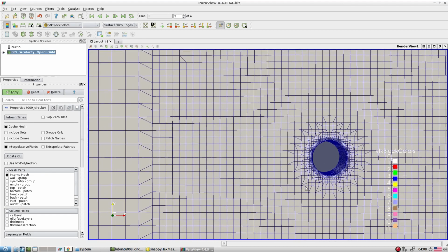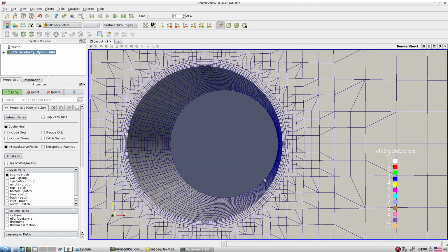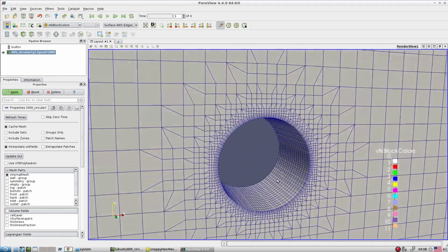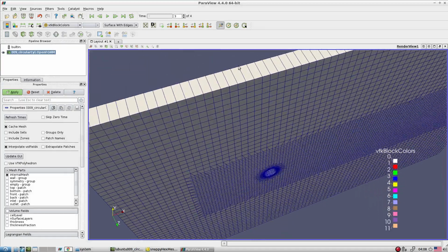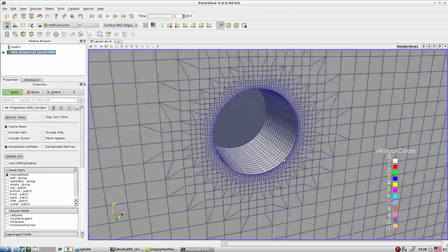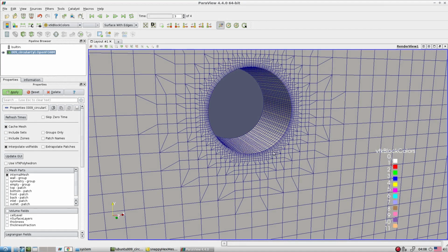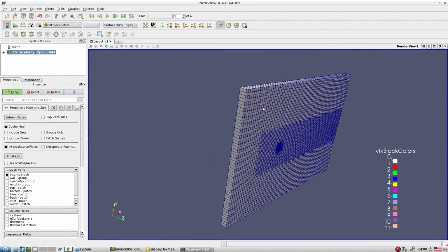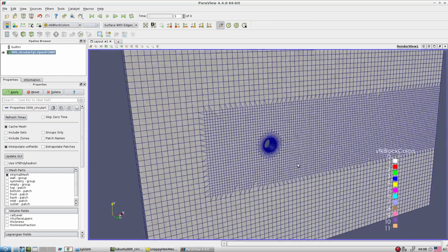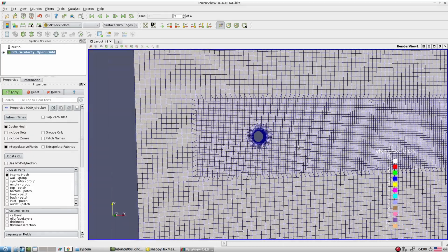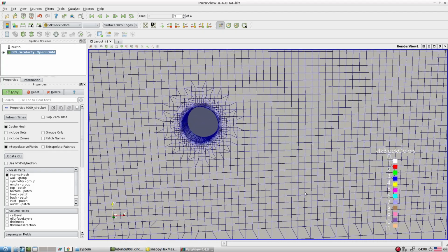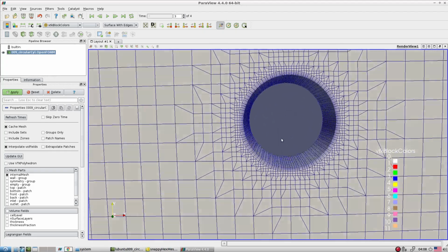Look, this is the mesh we constructed. But if you look at the mesh, it is still three-dimensional. Why is it a 3D mesh? Because in the Z direction inside the cylinder you have multiple layers. When we want a two-dimensional mesh, we require only one cell in the Z direction, like what we have here. But here we have multiple cells, so that does not allow us to run in the two-dimensional way. That means in the Z direction, the patches we would keep, let's say front and back, would be empty. It is not possible right now because we have multiple points here. So this is how one can quickly construct the mesh for flow over a circular cylinder.